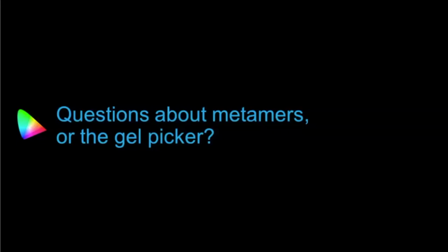Yeah. Peter asks, I tried it and it doesn't seem to change the RGB value. It's not going to change anything in RGB. Metamers only work in 4 color or greater systems. Metamers do not exist in 3 color systems. And those are color systems. RGBW, the W doesn't add any additional gamut. It only adds brightness, right? So if you're dealing with an RGBW, you're not going to have access to Metamers. You have to have an additional color in order to expand your gamut.